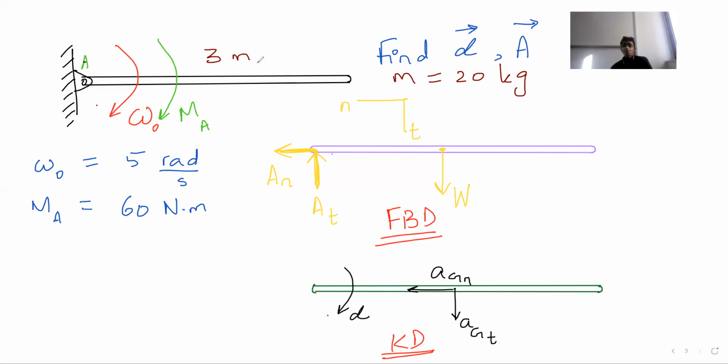So the first thing first, in an exam setting, you draw a free body diagram. I have to come up with my coordinate system. I think normal-tangential are perfect. Normal is towards the center of rotation. I always put my tangential towards the motion. I did not break my own method. This is towards the center of rotation and this is towards the motion, like in the direction of omega.